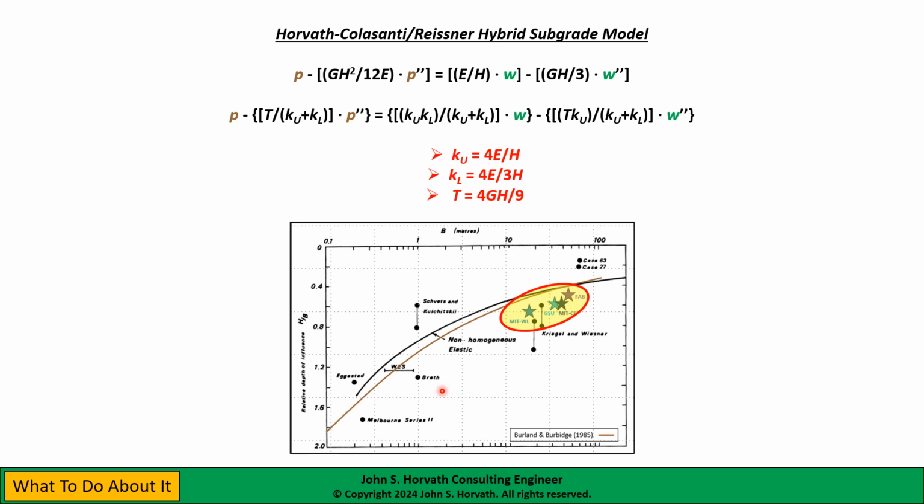So this is a very practical to use subgrade model. There is no reason why this subgrade model cannot be used in research and practice right away. And again, we've illustrated this with several case histories where I show you step by step how to use the model, then compare the calculated results to measured results with good agreement.